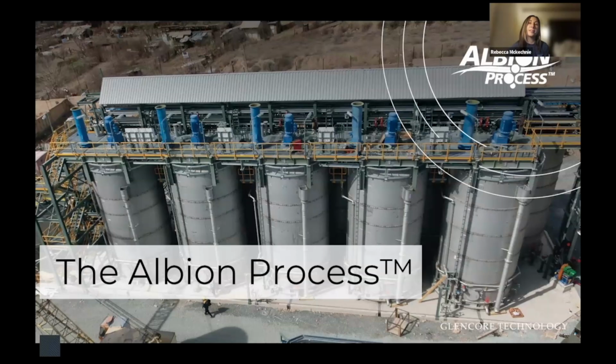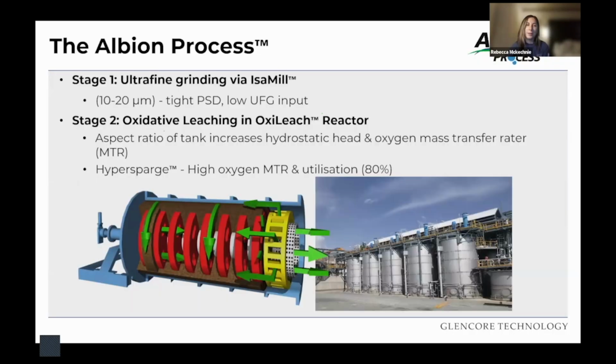So the Albion process is an atmospheric oxidative leaching process. It's been successfully commercialized in zinc, lead-zinc, copper, and of course in gold. The Albion process actually comprises two very simple stages, and it is as simple as it looks and sounds. So the first stage is a fine grind in an Isomill, as we talked about before, and it's the ability of the Isomill to achieve that really tight size distribution, not just a fine grind, but bringing that coarser top size down.